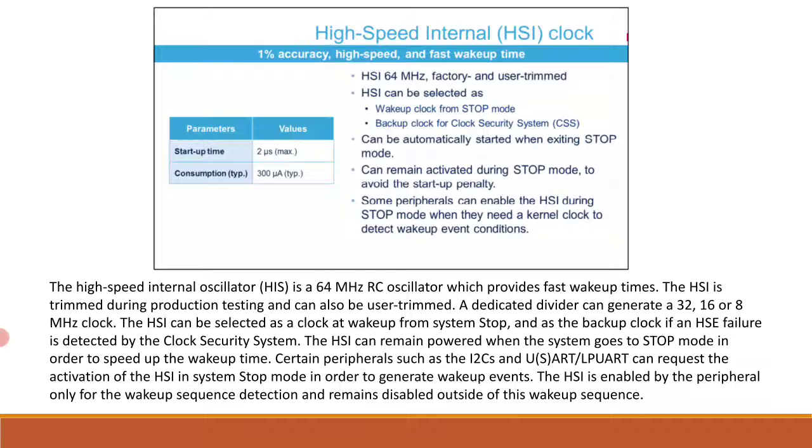The HSI can remain powered when the system goes to stop mode in order to speed up the wake up time. Certain peripherals such as I2C, UART, USART or LPUART can request the activation of the HSI in system stop mode in order to generate wake up events. The HSI is enabled by the peripheral only for wake up sequence detection and remains disabled outside of this wake up sequence.